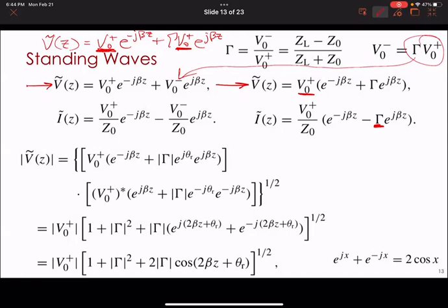And you can figure out now, you know how to calculate its waves in air, right? So we know the speed. Waves in air, just like light, speed of light. So lambda equals c, because we're in air, divided by f. C is 3 times 10 to the 8. F is 2.45 times 10 to the 9. You could get a number for that. Whenever you have screening, you want to make sure that the gaps in your screen are much smaller than the wavelength. So you inject these electromagnetic waves and they bounce all around in there like it's chaos, right?